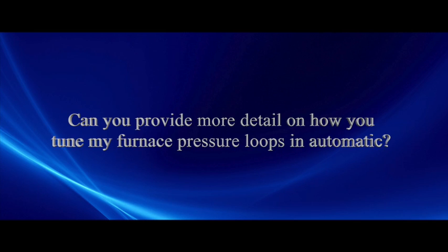And you've got to realize there's a compromise when we go for minimum peak error. What used to be thought of as the best tuning setting was quarter amplitude decay. Now these days people say, oh, that's horrible. And what's interesting, on the Automation Hall of Fame Awards, the trophy has a quarter amplitude response on it.